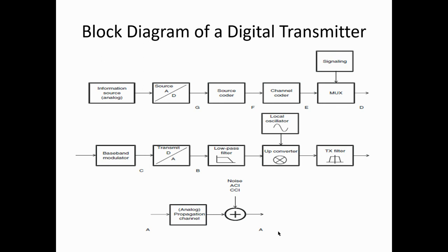And then we have a multiplexer. Normally data are transmitted as bits, or bits and bursts. So for that, n number of data has to be multiplexed and transmitted over the channel. Even if you are using MIMO, multiple users transmit at the same time, so the information is multiplexed together and transmitted in free space. That is called spatial multiplexing. That's a separate concept; we will discuss it in a later part of the units.